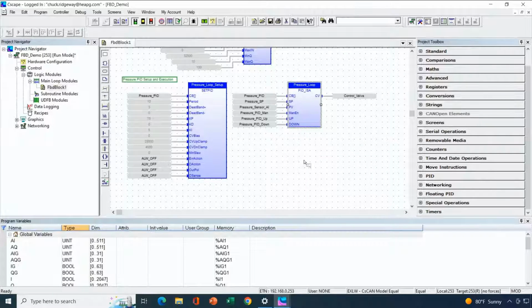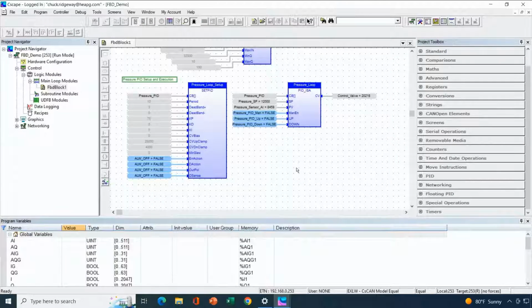This is just a real clear way to set up your PID so you can see what's happening. You can see all the values. These are just constants I have here. Everything that's a variable is clearly called out. So this is just really nice. And again, if we go into debug mode, we're going to get a pretty nice display where we can see what's currently on, off, etc. And for all of our variables, we're able to see their current values on everything that is a variable.